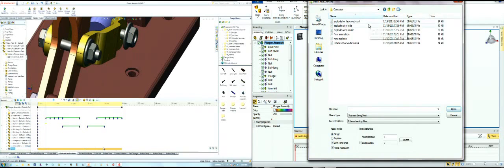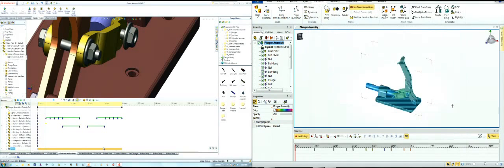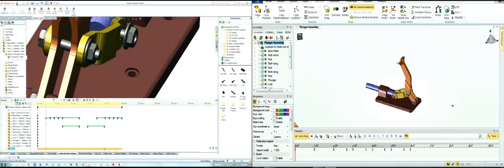The problem being, when the solver goes in here, it always moves things the closest direction, like a lot of things in SolidWorks. So I can't tell it to move over here and rotate 360 degrees because that's the same as 0. In Composer, she's got the ability to tell it numbers greater than 360 degrees, and because it goes in and puts those intermediate key points in there, that's a plus. Okay? I have other ways though.